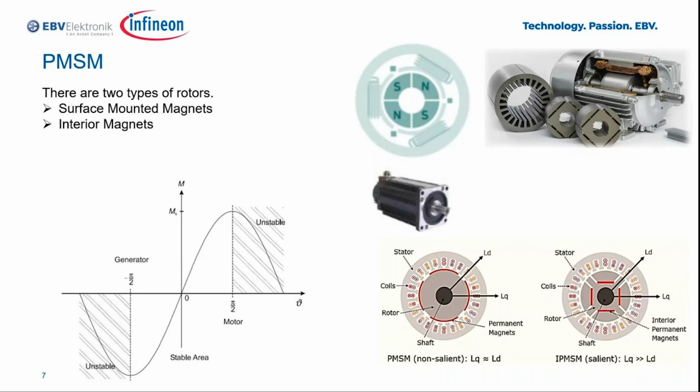To operate a synchronous machine at different torque-speed points, it is necessary to adjust voltage or current and frequency. Modern drives with PMSM are mostly fed by frequency converters to generate three-phase systems with variable frequency and voltage or current. Consequently, it is possible to control the speed and torque.